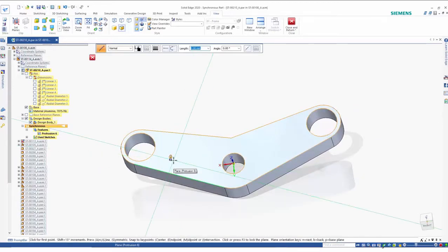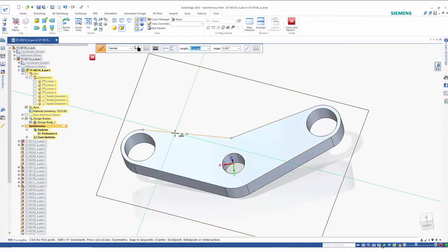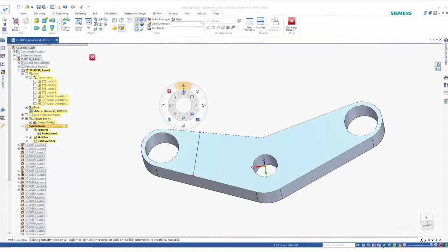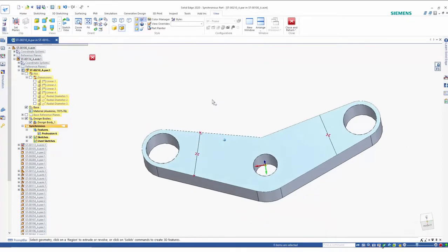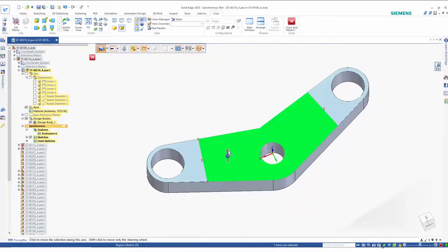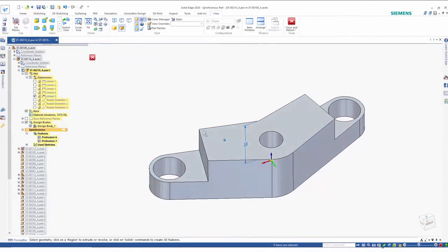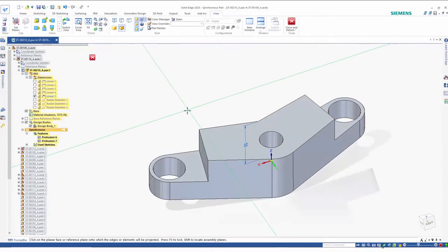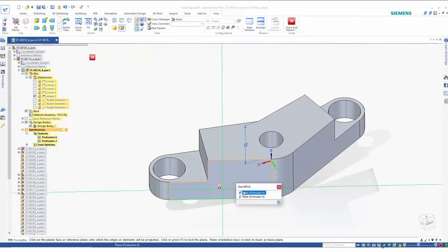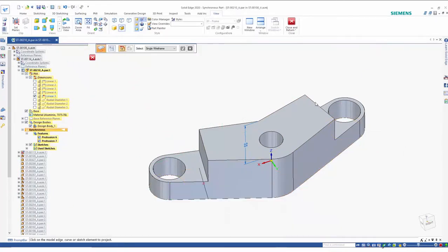As we turn off the PMI, we're going to sketch directly on the face of the part. Here, from just two simple lines, we can raise the center section of the part. Again, notice how Solid Edge automatically adds the PMI dimension to reference the height of the part. Next, we will easily copy the top edges down to the bottom face of the model, where this time we will remove material to avoid interfering with other components on the motorcycle.